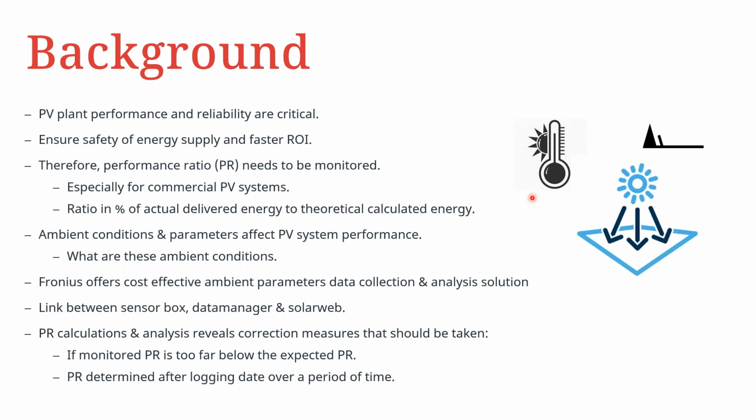So module temperatures could be affected, for instance, by the ambient temperature, but you could also have the formation of hotspots within the PV modules because of maybe some short circuiting or breakage within the modules. So when you're monitoring this kind of parameters, you are able to know whether you have abnormal behavior, for instance, for the module temperature, and therefore you take the necessary remedial actions.